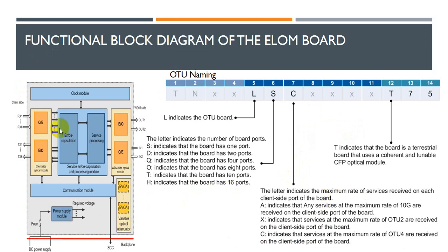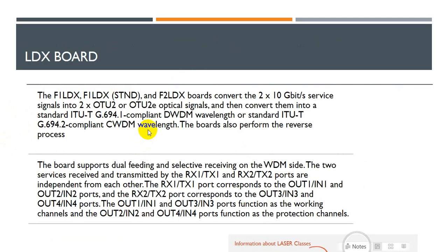We can see the block diagram or how it works. There will be an optical to electrical converter. You will have 8 inputs, 8 outputs, means one RX1 and TX1 will make one port, and then it encapsulates the signal, and finally it sends optical to electrical outside.